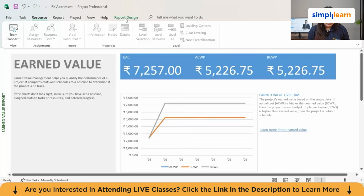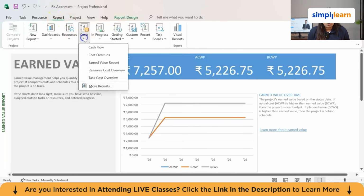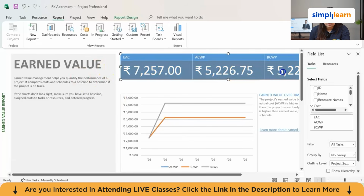Now, if you want to see in our case what the earned value report will be, you can come here in the report design. You can come here on Report, then go to Cost, and then click on Earned Value Report, and then you can see the report of the entire data that we have written here. The data that we have written is demo data. So over that, we can see small numbers, but we can understand. These calculations, we just understood how they are calculated.